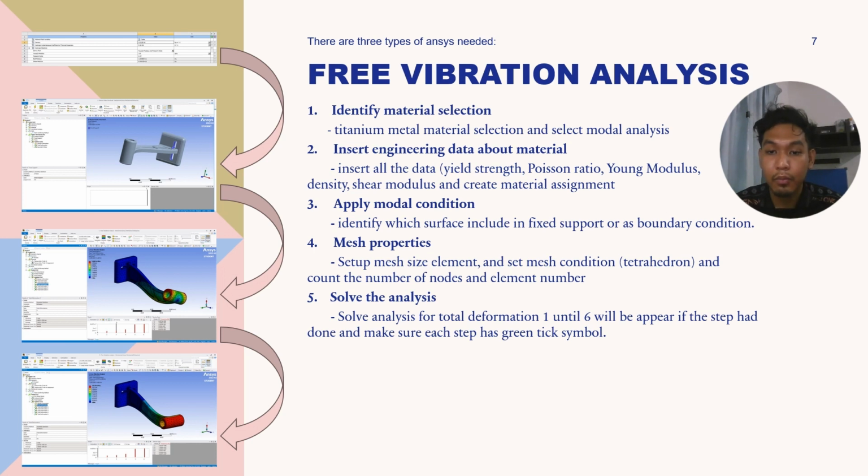And the third step is to apply model conditions. In these conditions, we need to identify which surface is included in the fixed support as a boundary condition. Solve the analysis for total deformations, deformation 1 until deformation 6.